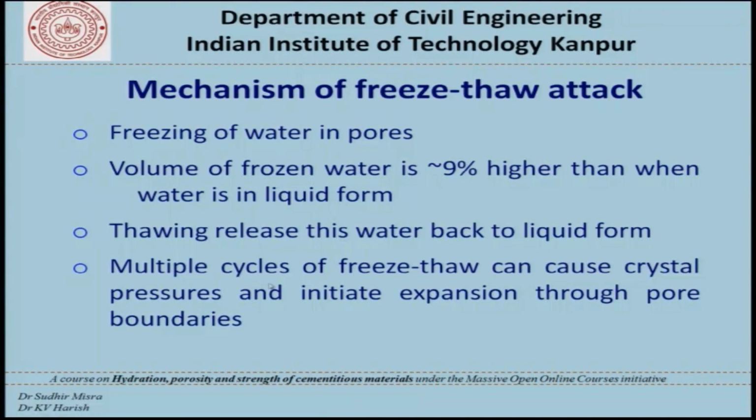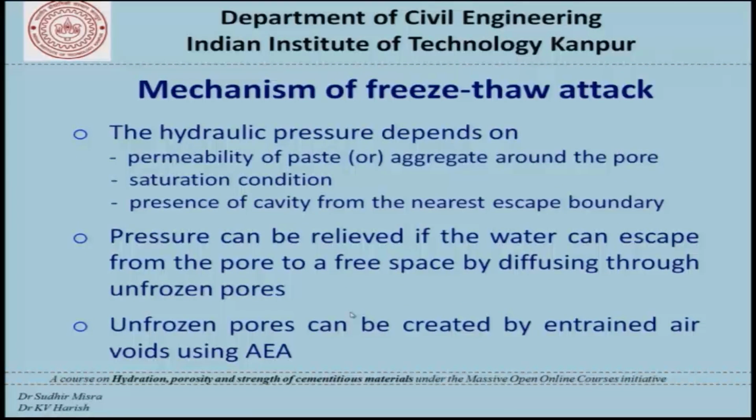So, multiple cycles of freezing and thawing may cause crystal pressures, primarily due to the ice formation, and this will initiate expansion through the pore boundaries. The hydraulic pressure that is built up in concrete will depend on the permeability of the paste and the permeability of the aggregate, especially around the pores.